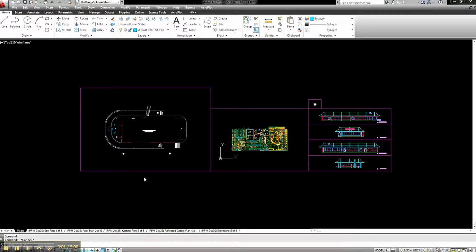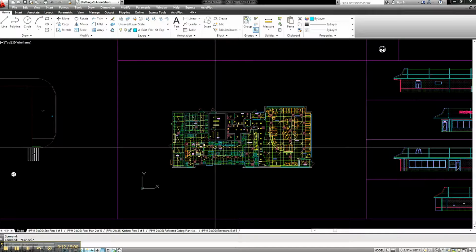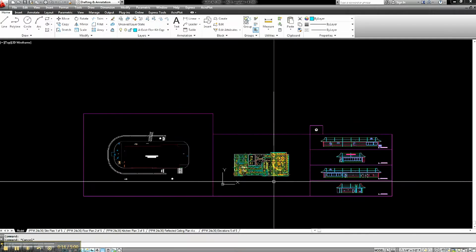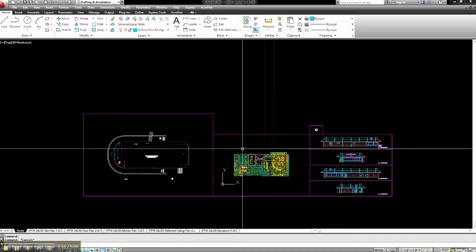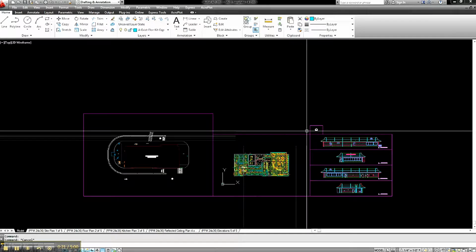So now in this video we're going to focus on the actual CAD setup, dimensions, and standards that are requested by this client. So you'll see here this is basically what our surveyor has given us. We have XREF'd our kitchen plan, and now it's time to do the rest of the setup. So I've provided these boxes inside the CAD model space that are used to center the drawing and set them up in the viewport.